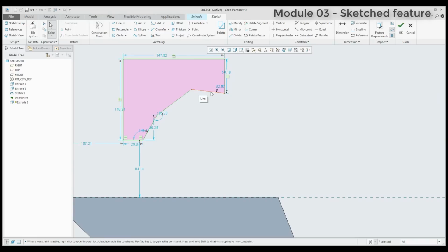Yeah, that point I have selected and placed not correctly. It was not selected horizontally. So you can click the right mouse button and over there you have the function set horizontal, and that line will be created horizontally. Or you can select another line and set vertical.